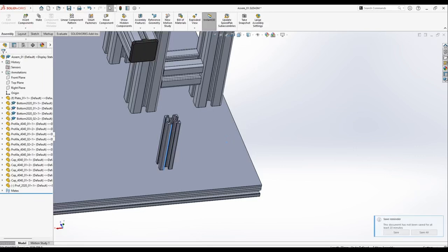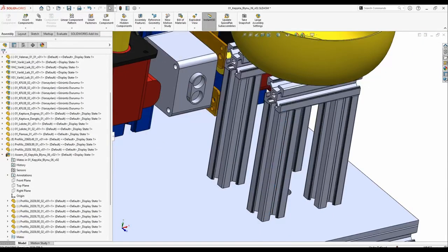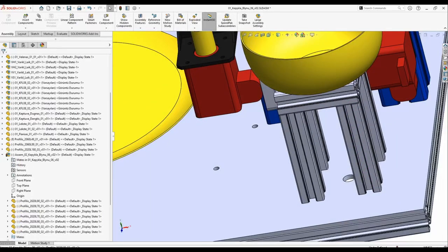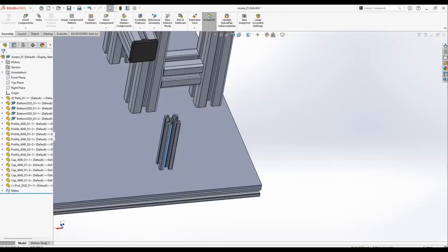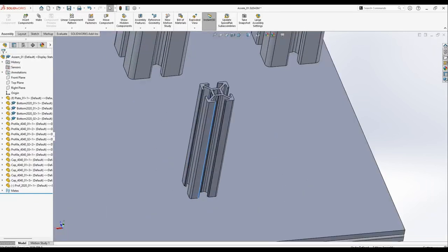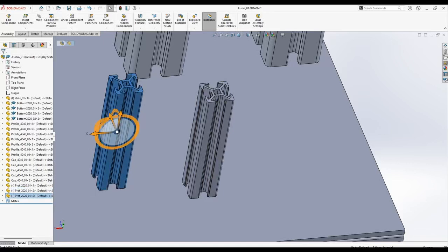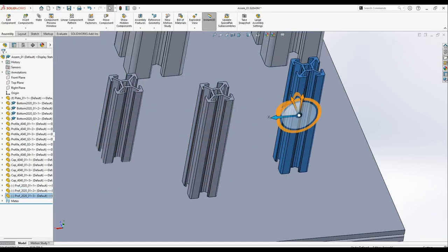Another what we need to add totally 4 vertical elements. 1, 2, 3, 4, and after 3 other horizontal elements. Good, we could do 2 ways. One way, copying Ctrl+C, Ctrl+V, and Ctrl+V. We have 3 parts, and with arrow we could move.